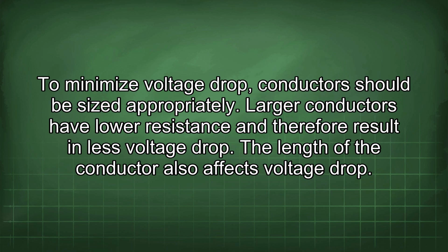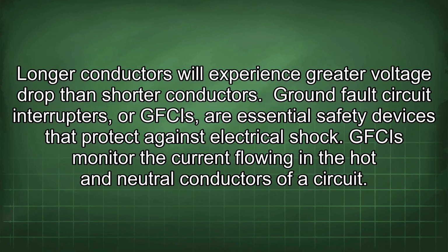To minimize voltage drop, conductors should be sized appropriately. Larger conductors have lower resistance and therefore result in less voltage drop. The length of the conductor also affects voltage drop. Longer conductors will experience greater voltage drop than shorter conductors.